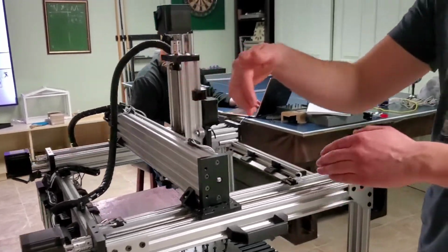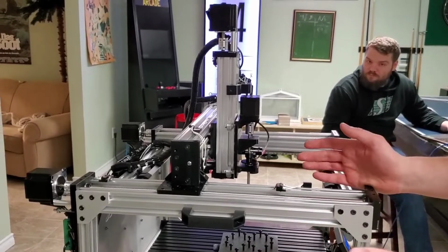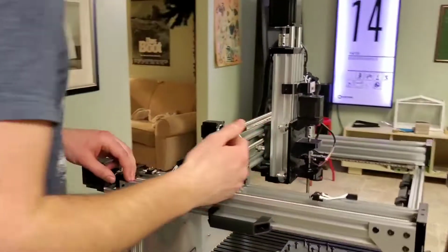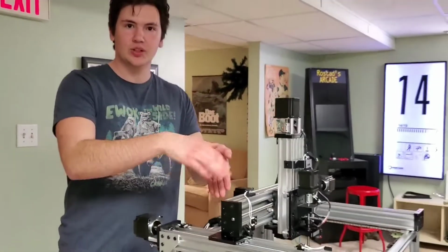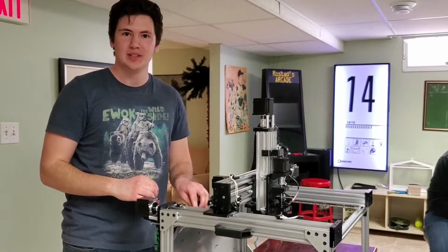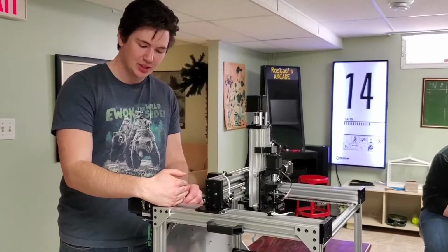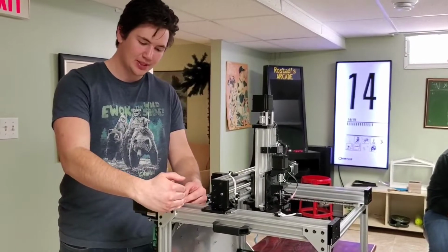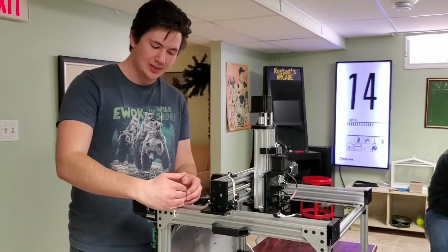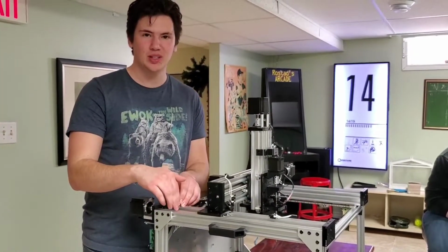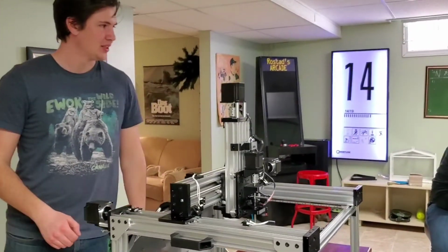Now, these of course allow the axes to move back and forth. One of the first things we had to do was figure out how we're going to make this thing go into its home position. We decided the home position would be in this corner here with the Z all the way at the top. When it's coming into home, it's going to hit the limit switch, bounce off, slowly come back, hit the limit switch, and then move off. That allows us to be at the same point precisely every single time. Now we'll demonstrate it finding its home position.